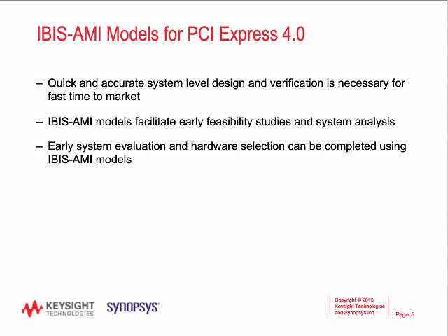IBIS-AMI models facilitate early feasibility studies and system analysis by enabling fast time-to-simulation results. Relative to circuit and transistor-level simulations, IBIS-AMI models using channel simulations are orders of magnitude faster. Early system evaluation and hardware selection can also be completed using IBIS-AMI models and fast channel simulations. Channels can be evaluated early, and hardware decisions can be made quicker without the compromise of accuracy.